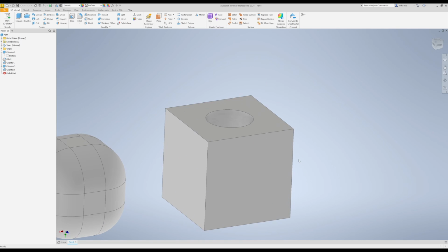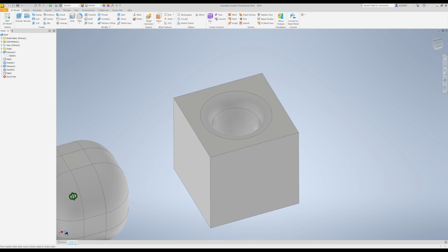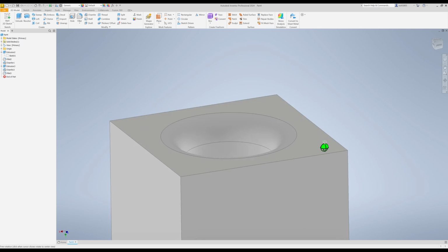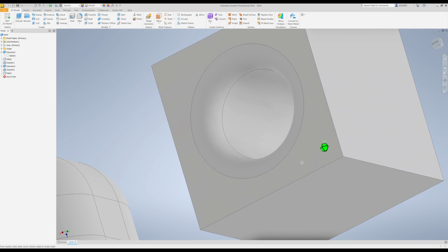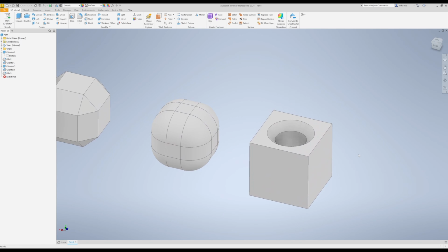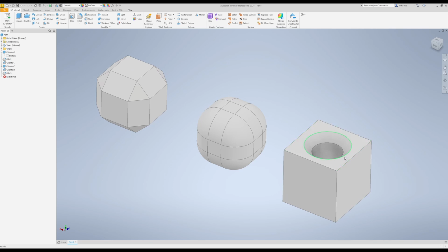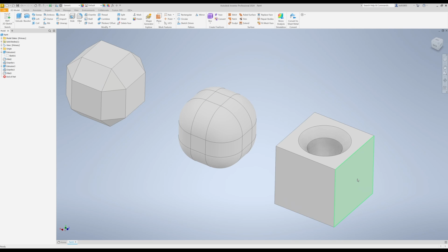And if I can show you on the bottom here, you can do the same thing with a fillet, which isn't as common because it doesn't work as well. But you know, you could if you wanted to. If you want to have a string pulled through this without it getting caught on any sharp edges, you can add a fillet. It kind of looks like a wormhole. So those are two other uses that you can use with the chamfer and fillet tools. And I use them a lot, honestly. All of these tools that I've shown so far are every time uses for me.